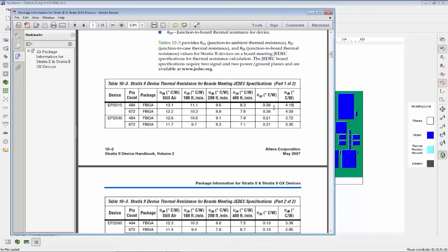watt. This is something called a 2-resistor model, and this assumes that the heat either goes up into the case or down into the board. Now, because this value is actually lower, I'm assuming that this chip is designed to have a heat sink on top of it, because all of the heat is designed to be extracted from the case.